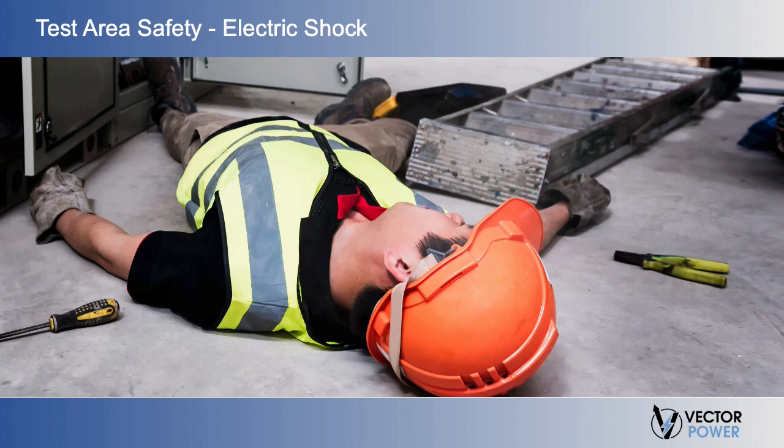A shock hazard is a source of possible injury or damage to health associated with currents through the body caused by contact with or approach to energized electrical conductors or circuit parts. Current through the body causes electric shock or electrocution. The potential difference a person may make between a conductive part of equipment or between the equipment and the ground is essential because this voltage forces current through the body according to Ohm's law. Therefore, current through the body increases with lower resistance and higher contact voltage.